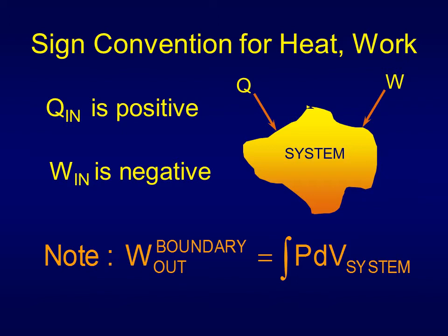So work is the integral of P dV. So pressure times the volume. Recall we looked earlier at force through a distance. Force dot dx is work. So we showed that that's also P times dV. So P times dV of the system. If the system is getting larger, then the fluid inside has to be pushing back the system, and that means that the system itself is doing work to push back the system. So work out, the integral of P dV, we call that boundary work.